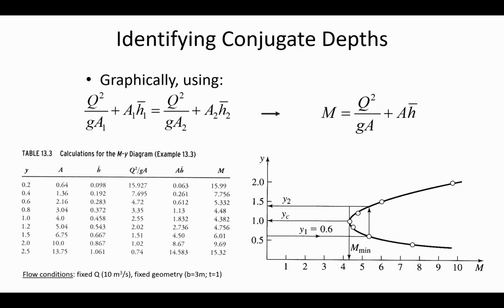So sometimes you'll be told how high the hydraulic jump is, and so you can find the two depths that go with it by looking at what point these two curves are a certain distance apart.